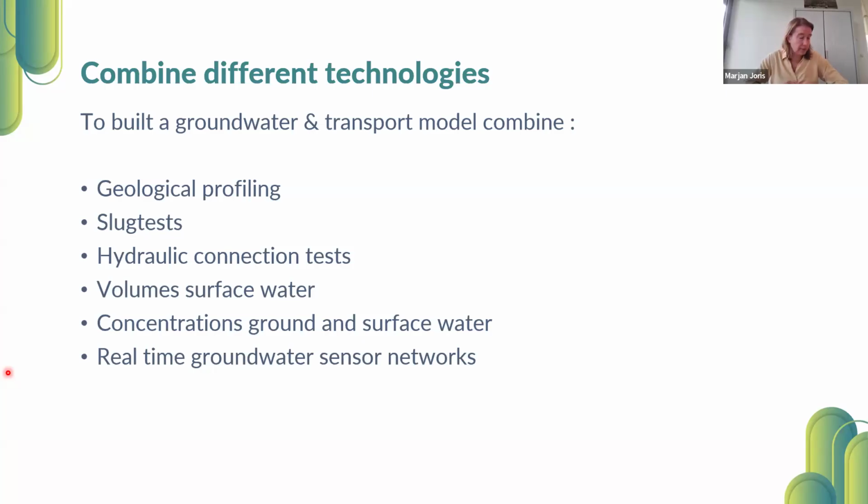We did measure in fractured bedrock, but then it is important to understand what you're measuring. So upfront of the iFlux campaign, geophysical investigation was done to understand where the fractures were present, and the monitoring campaign consisted of many samplers.